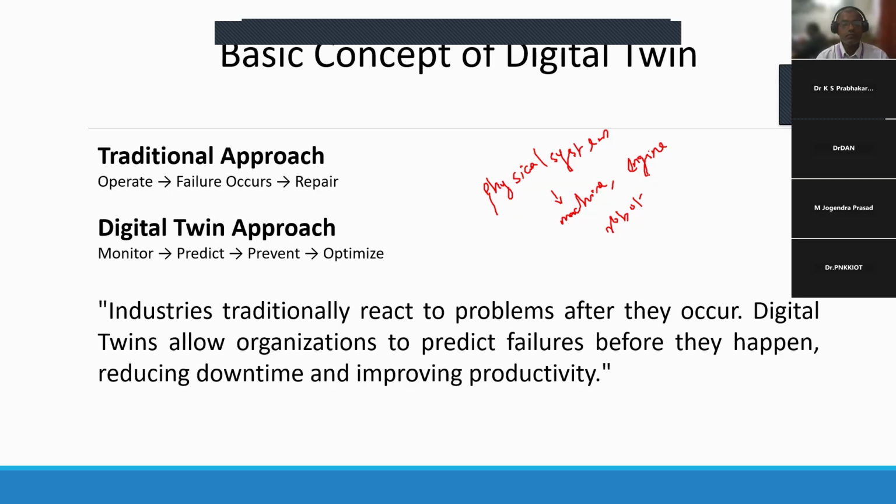What can that be? It might be the speed of the particular engine, or the pressure between the tool and its interaction with the workpiece component, or the vibration. To take this data, we need sensors to identify speed, vibration, temperature, all those things.